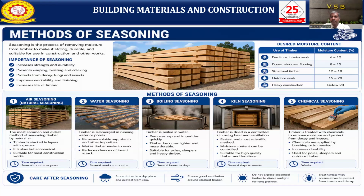In chemical seasoning, the timber is treated with chemicals to remove the moisture and protect it from decay and insects. So chemicals are applied by brushing or spraying. Okay, then it will increase the durability. This type of timber we can use for poles, sleepers, and outdoor timber. So we have different types of seasoning methods available.